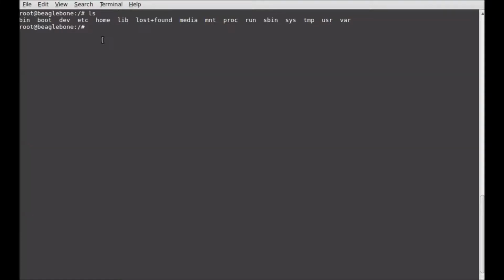Okay, so now I'm going to show you how to access the GPIO pins, modify the value, configure them for input or output, and export and map them to a file. In Linux everything is a file, so you have to mount a pin as a file. There you can change the value, and you can change the direction, whether it's an input or an output.